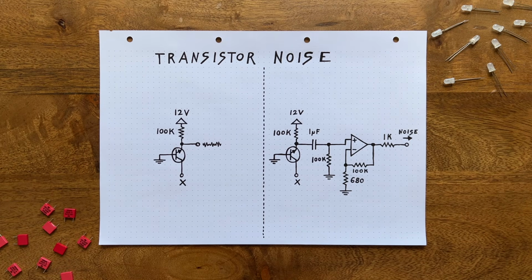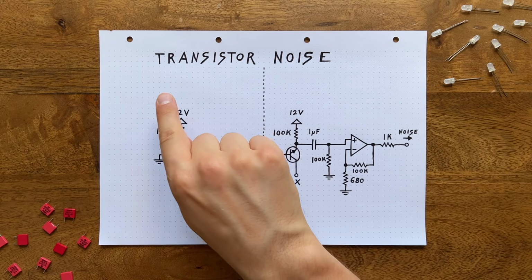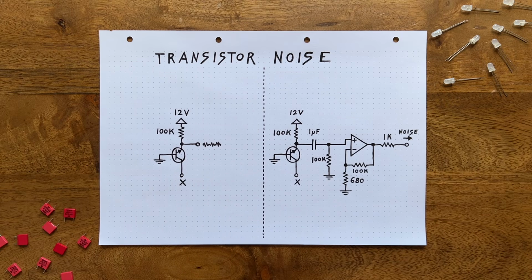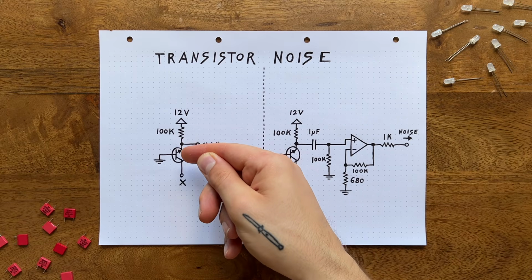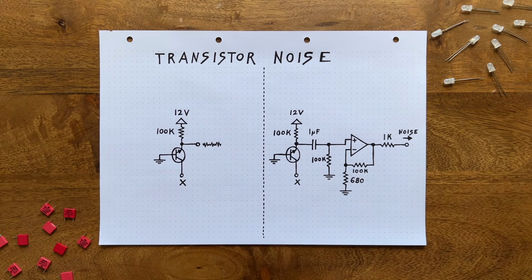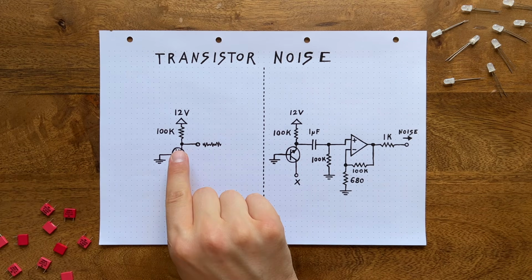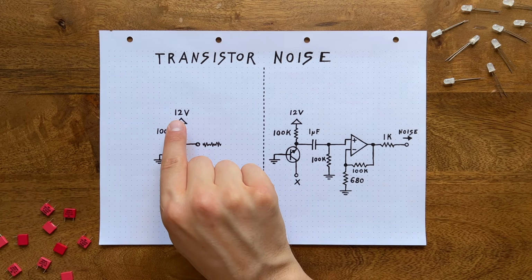To understand that, let's first assume that we've dialed our supply voltage down, below the 6 volts threshold. Now, no current flows into the transistor's emitter, because the transistor is not breaking down yet. This means that the pushing force, which a voltage essentially is, does not actually push any current through the resistor. So the voltage at this point is the same as it is above the resistor.